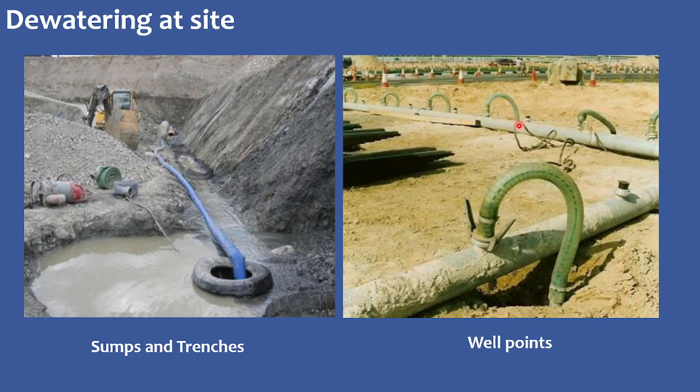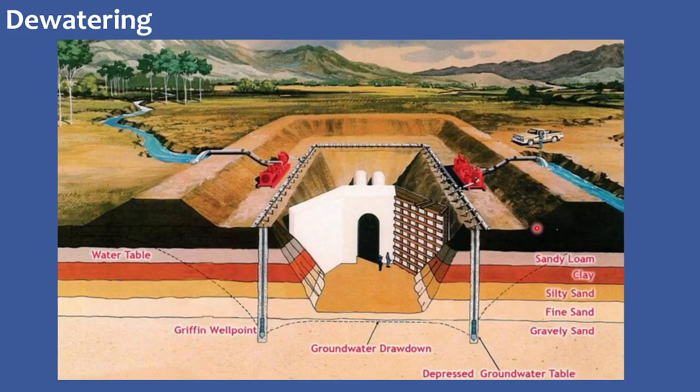This is the well point connection example. Here you have a main pipe, and then you have the sub pipes. These sub pipes are embedded into the wells, and these wells transfer the water from the groundwater table to the main pipe, and this main pipe further transfers the water to nearby water bodies.